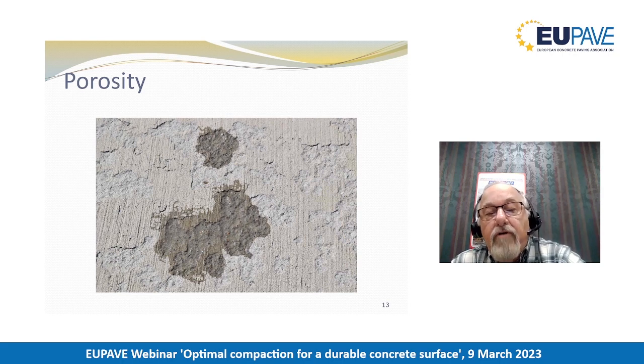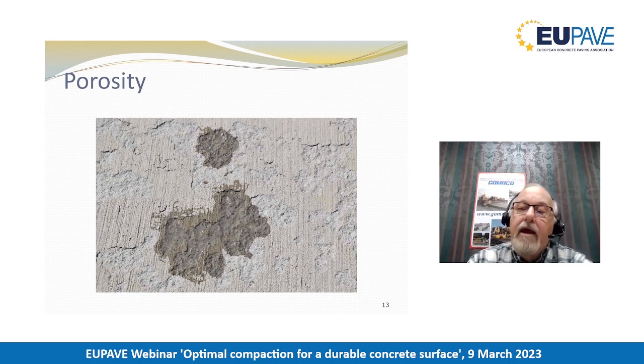Not only was the surface friable and scaled off, it was also very porous. I took a bottle of water and poured it on the surface. Almost instantaneously, the surface absorbed the water I'd placed on it. Now you can look ahead and say, if that is the case, then this pavement is going to absorb water at every rainfall event, every snow, every ice event. And because water expands roughly 9% in the porous structure of this concrete, it's going to continue to scale. So we had to do some remedial measures that we'll come back to in a second.